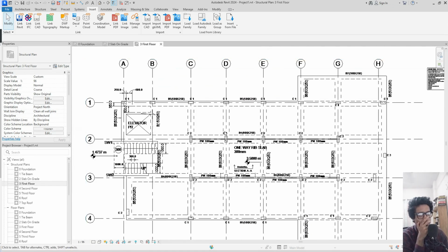I will create all these beams and place them on the first floor, and you can see these hollow places. There will be a beam system, I mean a bunch of beams, or a girder system, or you can call it a joist system as well. Joists are small beams, beams with small cross-sectional properties.